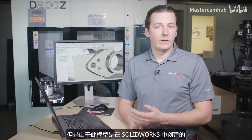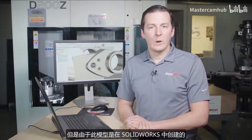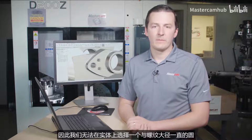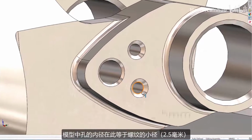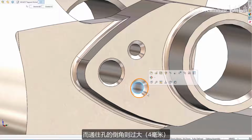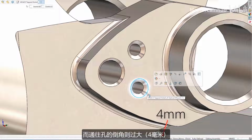The thread mill toolpath requires a series of equal diameter circles to denote the position and major diameter of the holes to be machined. But because this model was created in SolidWorks, we can't select a circle on the body that is equal to the major diameter of the threads. The internal diameter of the model's hole here is equal to the minor diameter of the threads, and the chamfer leading into the hole is oversized.